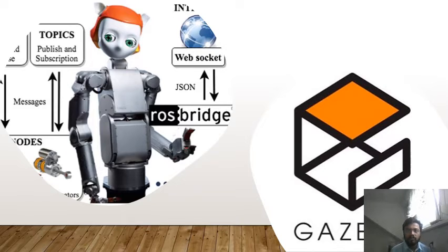Obviously, we do not want our robot to fall, therefore we need to create a simulated environment where we can simulate the robot's movements and generate data. For this, we'll use a physics-based simulation software, Gazebo. Gazebo also offers inbuilt sensors to simulate sensor data. That is what we need. We'll also interact with the robot inside Gazebo with the Robot Operating System, ROS.